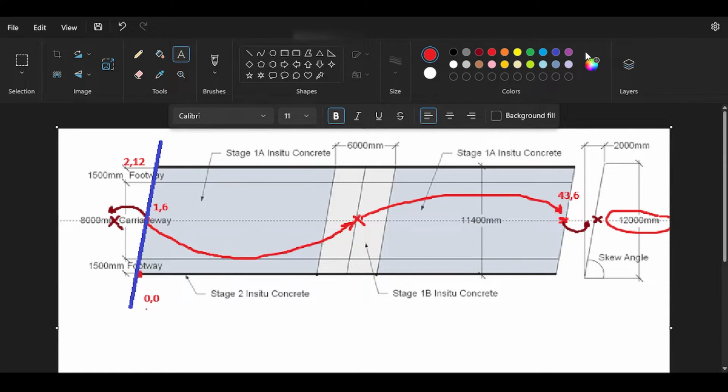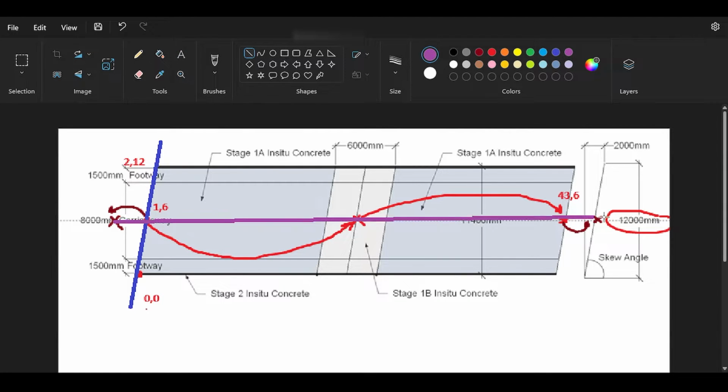A carriageway is basically the loading area. The carriageway needs you first to define the line, and then you will tell how the offsets look for that line. A carriageway will allow you to define a footway and draw a road and define another footway. Now for that, you would need to know exactly what the offsets are. It seems the offset for the footway is from 4 meters to 5.5 and from negative 4 meters to negative 5.5, whereas the carriageway is from negative 4 to 4.